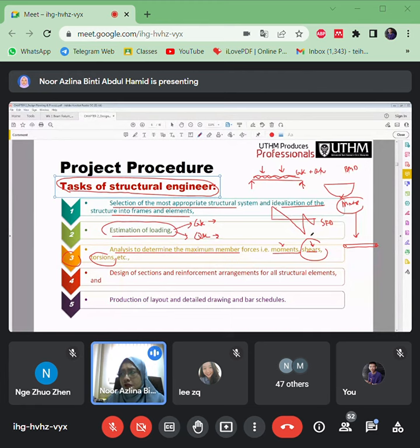Let's say from this SFD, what's the maximum shear here? Let's say this is the shear maximum, Vmax. So this Vmax is very important for you to decide the shear links. This Vmax will be used to design the shear links. What are the spacings between the links, what is the size or diameter of these links here? Is it using size 8 or size 6?